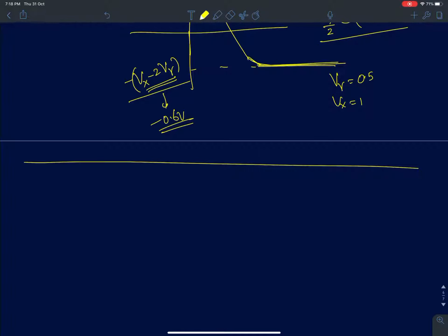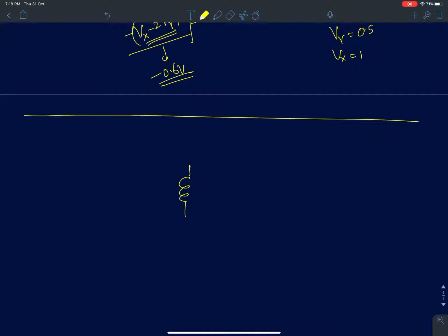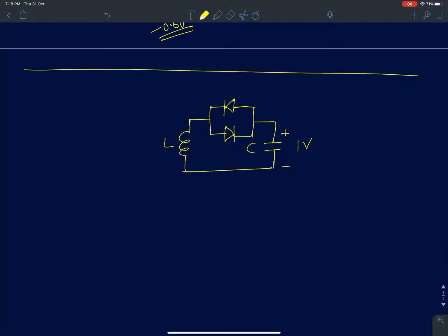So now the next circuit is, we'll introduce two diodes connected back to back in parallel, shown in this way, and see what happens to this circuit. For the first case, I'll assume that the cut-in voltage of both the diodes is 0. In that case, I take this composite combination of two diodes connected in parallel with the terminals reversed,